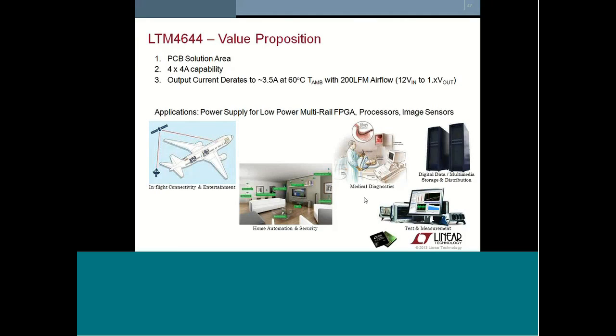If thermal derating is of any concern, I encourage you to follow the analysis procedure described in the maximum operating ambient temperature section of the data sheet of this LTM4644. You can see that the number of applications to which this particular micromodule can be applied is numerous.